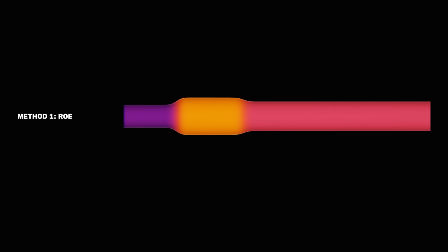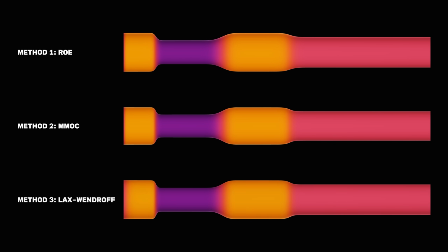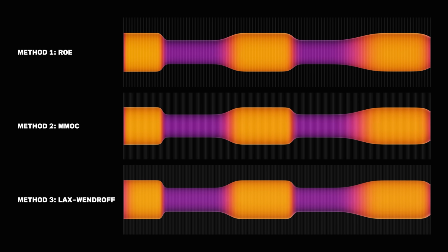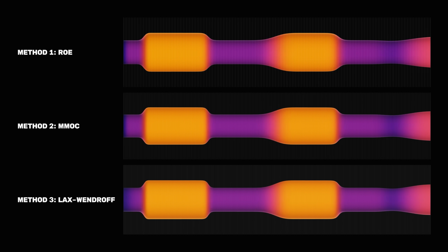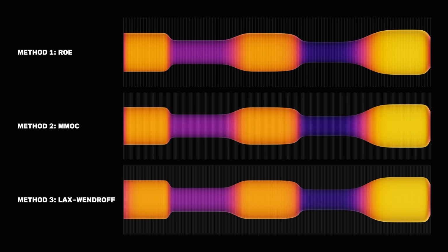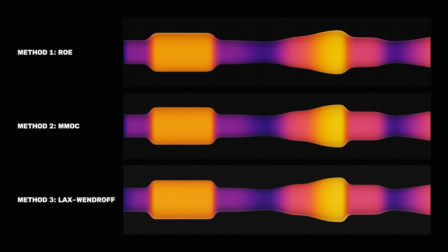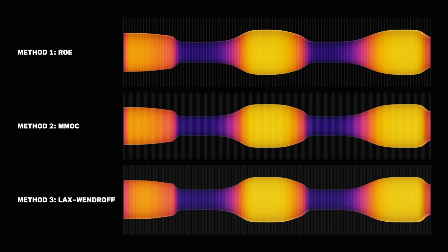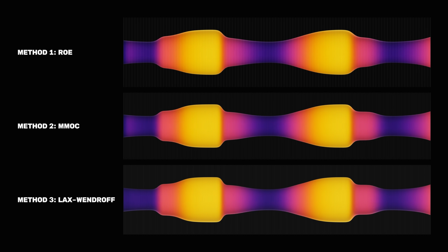To make sure this was actually a theoretical limit and not simply an implementation error, I implemented multiple fluid simulation techniques, which theoretically must all converge to the same solution, and they do, albeit at different rates. Many of these techniques do not have any code or conceptual commonalities, yet they still give the same answer. So it is very, very unlikely for all of them to be implemented wrong in the same exact way. Therefore, we can rule out any major implementation errors in the simulation.